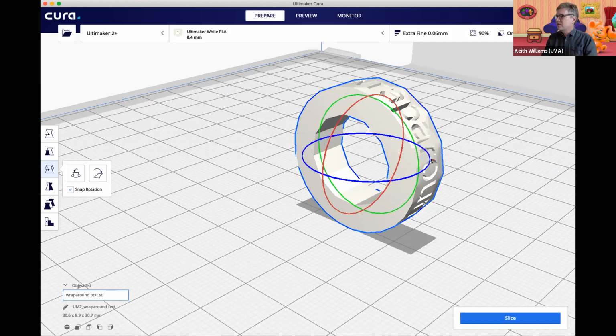If you have something that you want to print in super duper high resolution, you want to make a realistic bust of your instructor and put that on the top of your ring, right? And your beloved ENGR instructor, and you want to make that face super realistic with a big nose and everything and the glasses, then you better do high resolution and just have it printing in the lateral direction, right? If you're layer limited in that, then it's not going to look good, right? If you're going to put TJ up there, if you're going to put a rotunda or something like that, then you probably want to print it with the really, really fine features facing upwards.